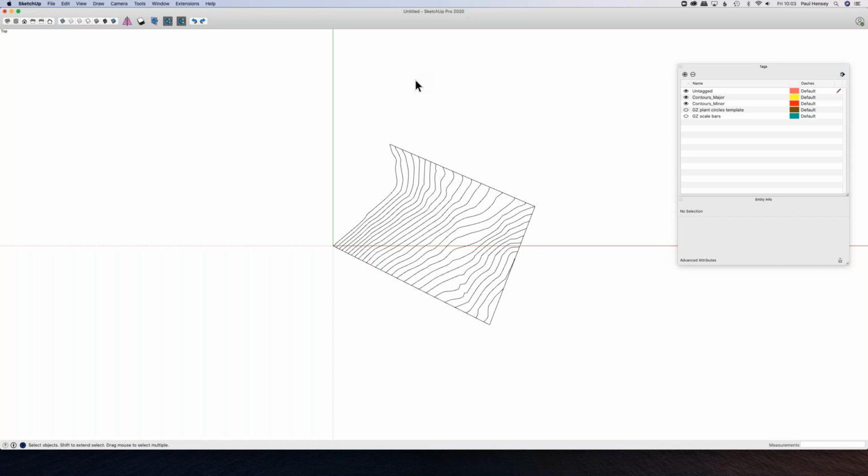If you ever see architectural models, which I think in themselves are beautiful things, the terrain is invariably, or was invariably, represented by slices. You would take each contour, trace it, cut it out of cardboard, and lay it in situ. And so you end up with what is affectionately known as a stepped terrain model, sort of like tea plantations going up a hill. And we can recreate that very easily in SketchUp.